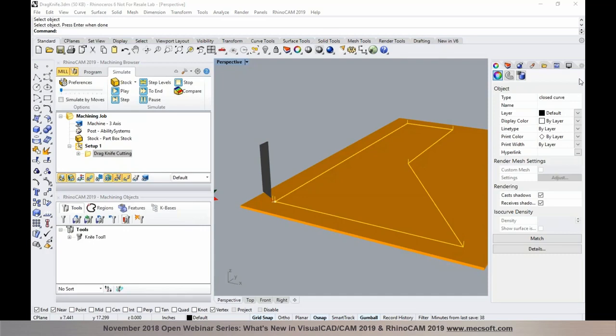What we allow is when we retract back, the tool retracts back to a swivel height, and then we put in an arc motion that will allow the mechanism that's attached to the tool to actually orient the cutter in the right direction. There's a very commonly used drag knife called Donek, and you might be familiar with that. There's a lot of information on the Donek website, and that'll give you more information about how we handle that type of knives.